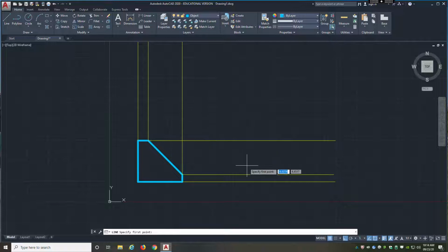And again, we're going to start with a line. Where do I start, right? I can start at the end point. This might be too far away. I can start at the midpoint of this construction line. Same thing with the ray. Where exactly do I start? That's really up to you. You kind of have to gauge whether or not you have enough room for dimensions. And the truth is that after you're done drawing the additional views, you can always move them over or move them closer or farther away so that you do have room for dimensions. So it's not like you have to put them in a certain distance.